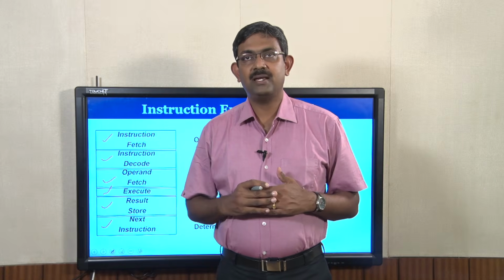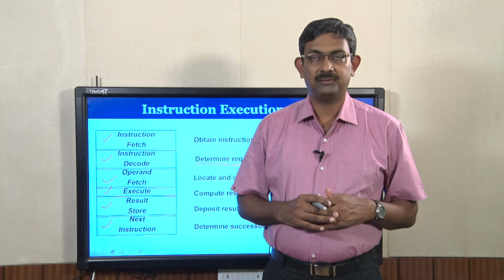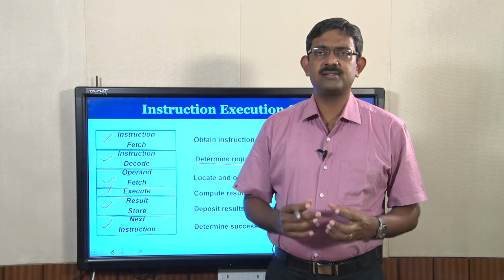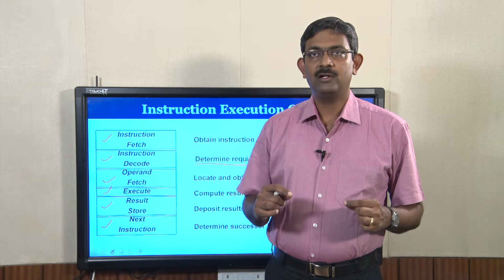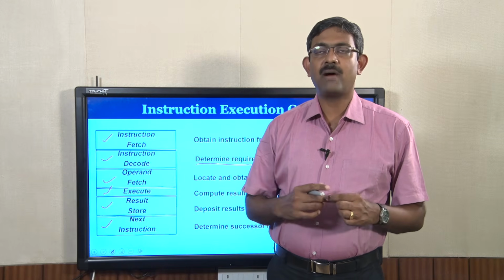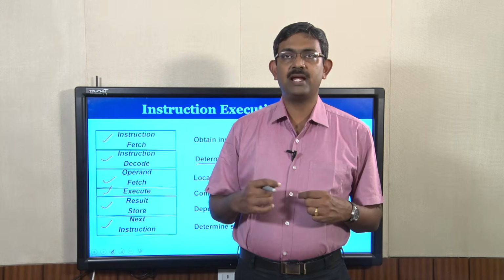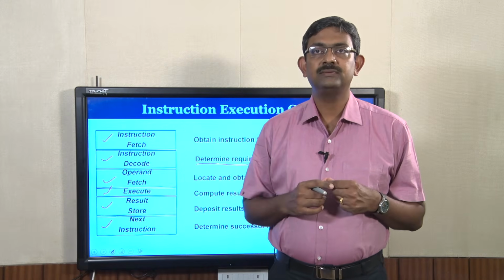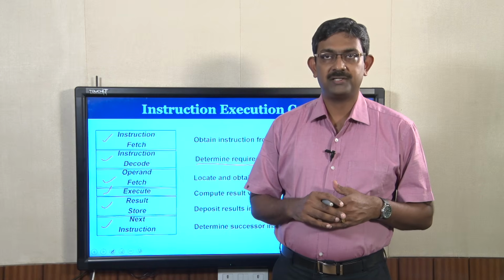The second aspect is the operand, which specifies where the operation is to be done. So, trying to understand what the opcode and operand is, that is called instruction decode, and followed by the decoding, as a byproduct of decoding, the processor has to generate appropriate control signals in a sequence to carry out the execution of the operation.